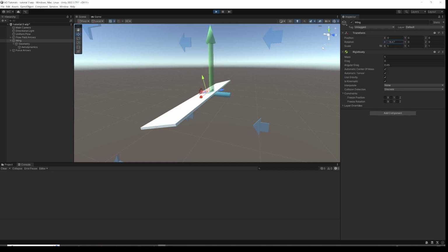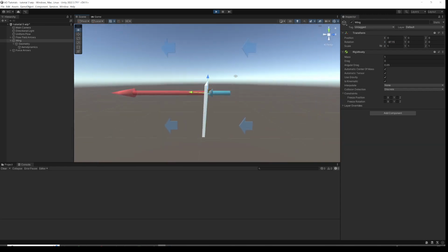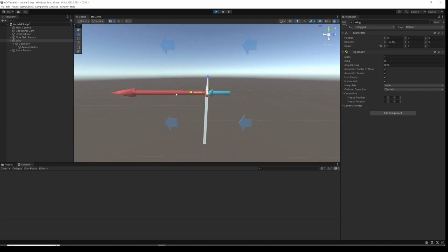And what we saw there was that as you increase the angle, the lift goes up, but eventually you reach a stall, at which point the flow changes behavior over the wing and the lift drops off. And as we're going further up, the lift is now coming down, so we're getting less and less lift, but the drag is going up. And often when you stall a wing, the thing that's most concerning is not necessarily the loss of lift, it's the massive increase of drag. And if we go all the way to around 90 degrees angle of attack, we see that we've got no lift and lots of drag. And carry on round.